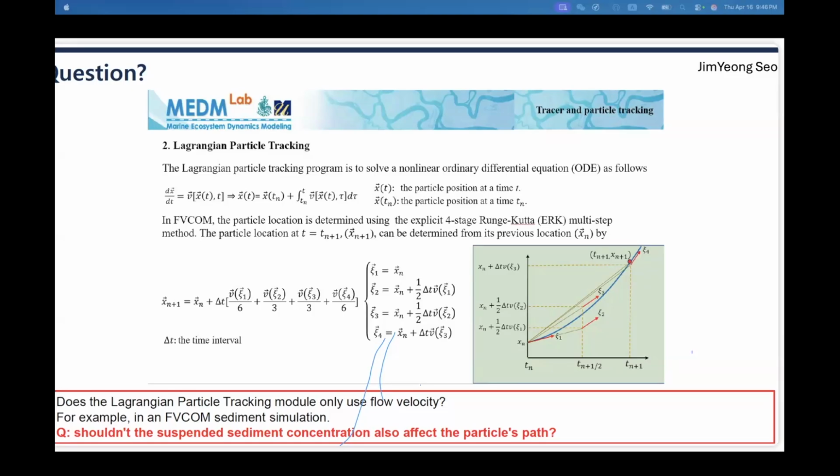In the global ocean model, horizontal diffusion is set on the order of 10 to the power of 6 square meters per second, which is huge. But when you look at the coastal region, near the tidal mixing front, like a short, big front, and you do dye experiments, the horizontal diffusion is more like 10 or 20 square meters per second.